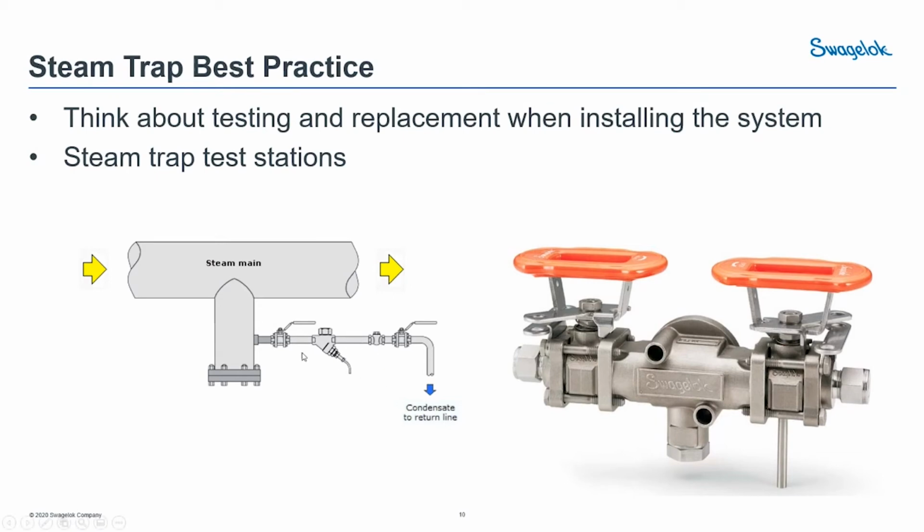So one thing that we offer here, another option instead of the sight glass, is put a tee with a valve. And what that allows you to do is you can turn off the condensate downstream line and open up this vent valve. And when you open that vent valve off the trap, you should be able to see the steam trap cycling. So it gives you a visual indication that the steam trap is cycling properly and not blowing through.